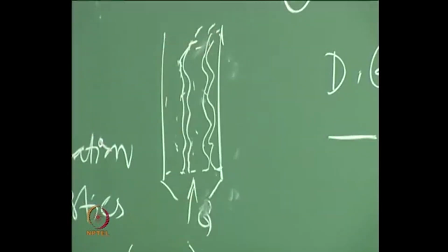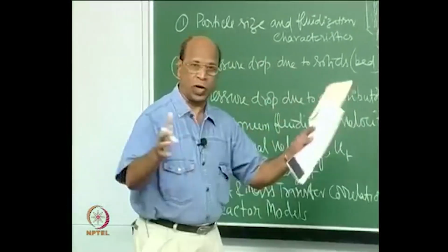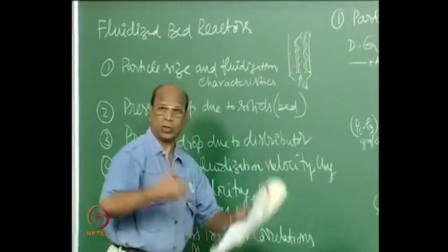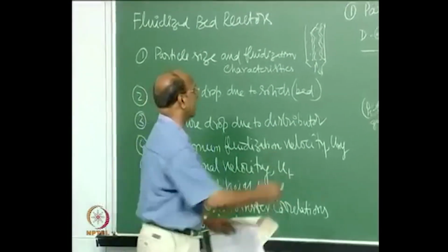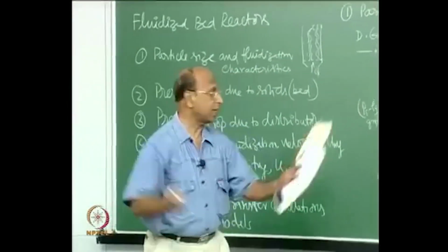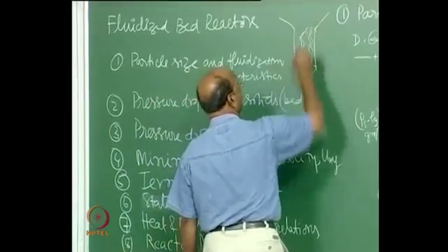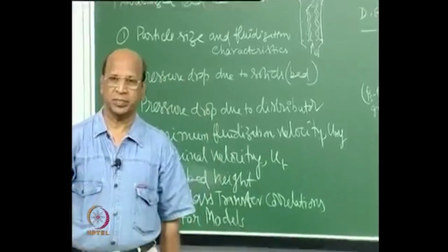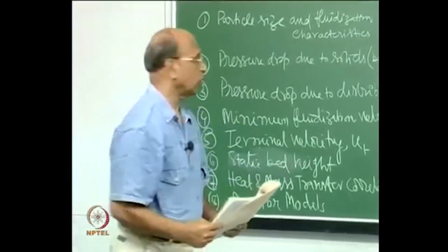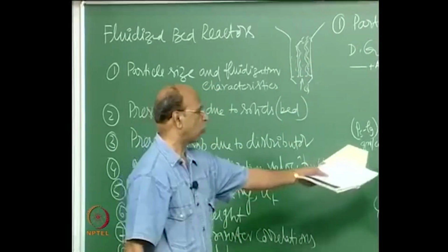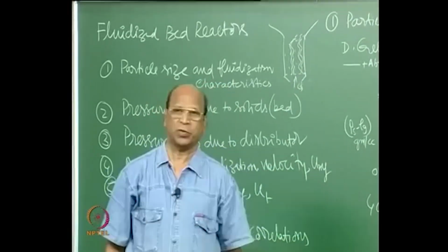But if you go on doing that, all the snakes will become one because they coalesce together, and then you have fluidization, but all the powder may be thrown out. So you can have a bigger cross section, so that even if it is thrown out, it falls back again. This kind of possibility is there with cohesive powders, which is why they are very difficult to fluidize.